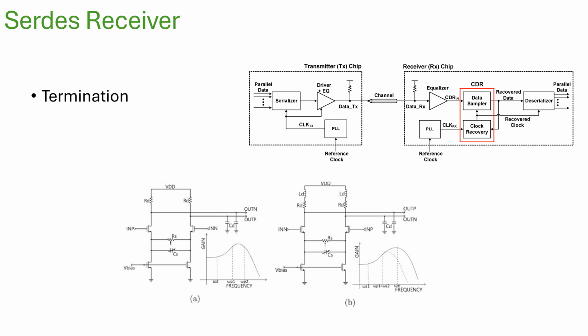Other than these things, because it is a high speed receiver, termination matters. SerDes is very high speed data transmission, right? And the signals are coming from the outside world, like between chiplets. So proper termination is important. And if it is connected to the external world, we definitely need a serious ESD protection scheme. Our regular old style may not work because these are high speed signals. You should not attenuate them, you should not be a load for them.